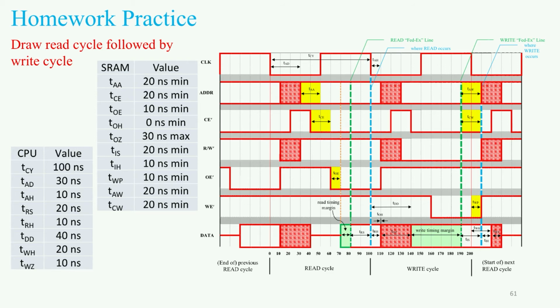And how does it do that? Right, because the SRAM is reading, if it's a write operation, that means that the SRAM is reading it off of the data bus and it's going to store it inside the SRAM. It does it based on the write enable bit. Okay, so the clock transitions to the high state, and 10 nanoseconds later because of glue logic delay, the write enable bit falls low.